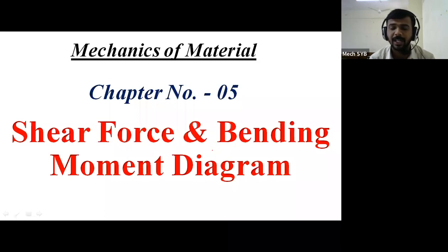Therefore, what is the first condition? The beam should be subjected to some amount of forces. It may be subjected to a point load, a uniformly distributed load, a UVL, any load. Due to that number of loads, there is a possibility of development of shear force and bending moment, and those values we have to calculate in this chapter number 5. At each and every point present on the beam structure, we have to calculate the shear force value and the bending moment value.